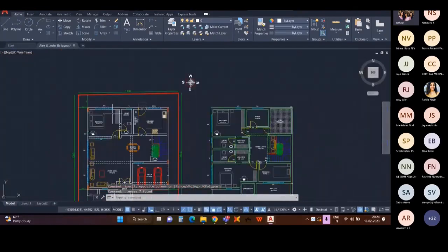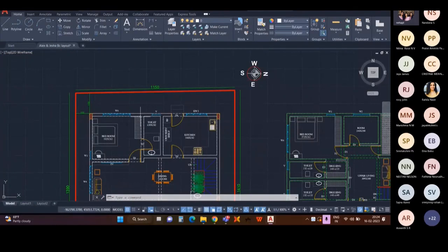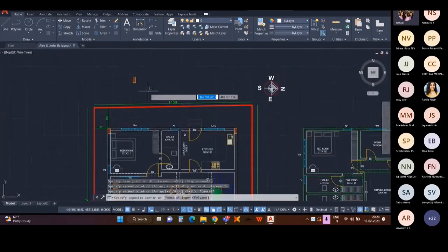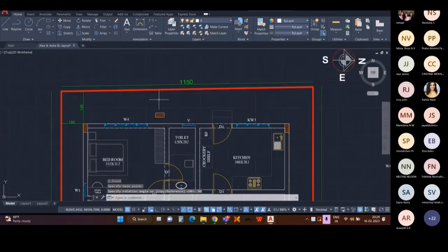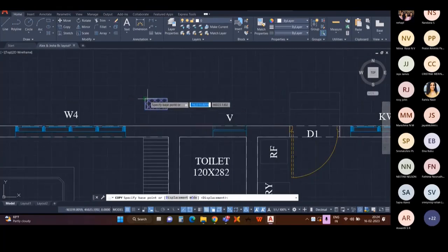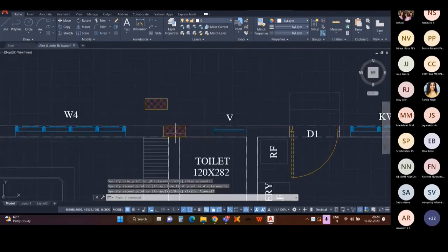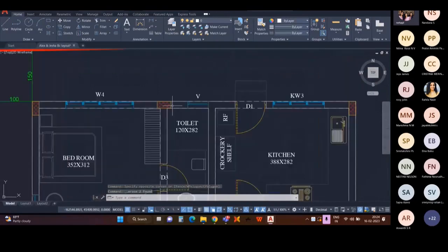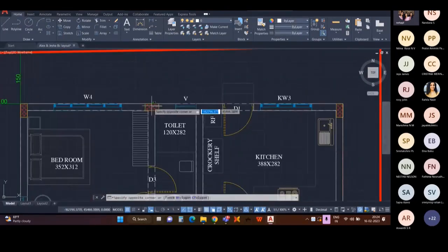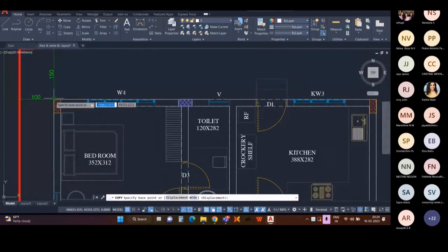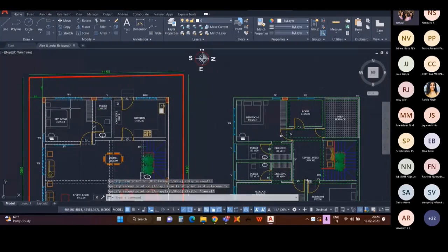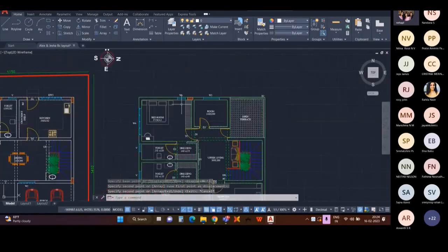Now let's find how we can place a column. We need a column here. So we will be rotating that column 90 degrees. We will be changing the orientation. Now I have placed a column in this direction, and let's check how it is in the first floor. When we place a column in the ground floor, we need to check how it passes through the first floor too. So I have oriented this column in this direction and I have pasted it in the first floor.